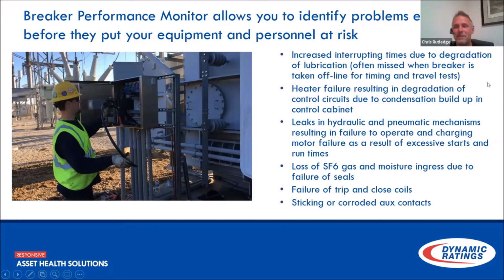Okay, so kind of a review on this. Increased interrupting times due to degradation of lubrication. And again, if you're only running offline tests on your equipment, you're not going to catch a lot of this. The utility I came from was doing only timing and travel offline for years and years. When I became asset manager, about 4 years before I left that company, I implemented some first trip testing, and it was amazing the number of breakers we found that were slow on the first trip, that we had no idea we had problems with.